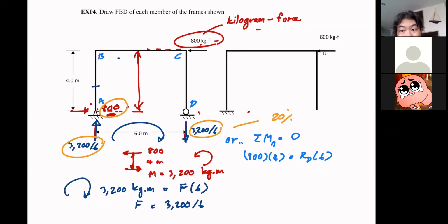So I can tell you now that when you try to solve the problem, the first thing you should do is complete everything step by step, and that is, complete the free body diagram of all the members first. This is not just about grading your level. This is about the practical purposes of your work as well, because if you can complete the free body diagram of all the members, you should know right away whether or not your equilibrium is correct.